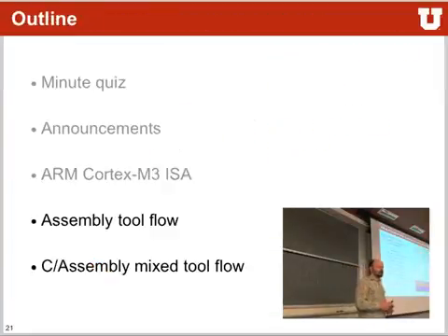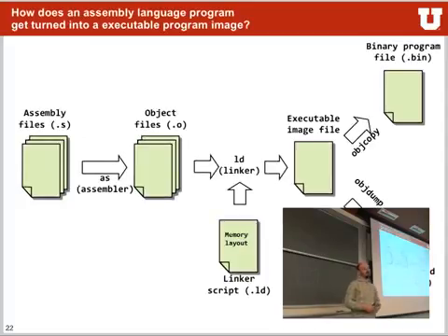How does this happen? Well, that's what we're looking at now, the assembly tool flow. So how do we go from your assembly code down into the binary code that's actually going to get uploaded in your microcontroller? Because there are a couple of different steps that are actually happening before this is possible. First, you have an assembly file. You use the assembler to make this into an object file. You then use a linker with a possible linker script to tell where this now all belongs to in an executable file. Now, the problem is the executable file is just kind of like a bag with all the information inside of it. And from there, you then use a different tool, objcopy, to make this into a binary program file. This is then a file that's used for certain applications to program your microcontroller. So you can see it's a fairly long chain until you get to your binary that you can actually upload in there. And each and every step does something very specific, and we will look at them now in detail.